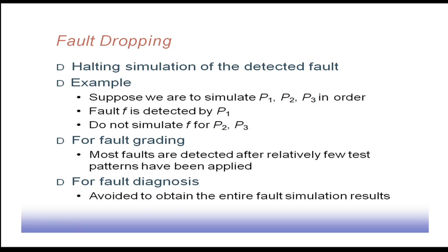Now when we have a large number of patterns, the remaining patterns may not be very effective in detecting many of the faults. So fault dropping will help us, because those faults are already detected, so we do not simulate them further. However, there is another application of fault simulation which is known as diagnosis.